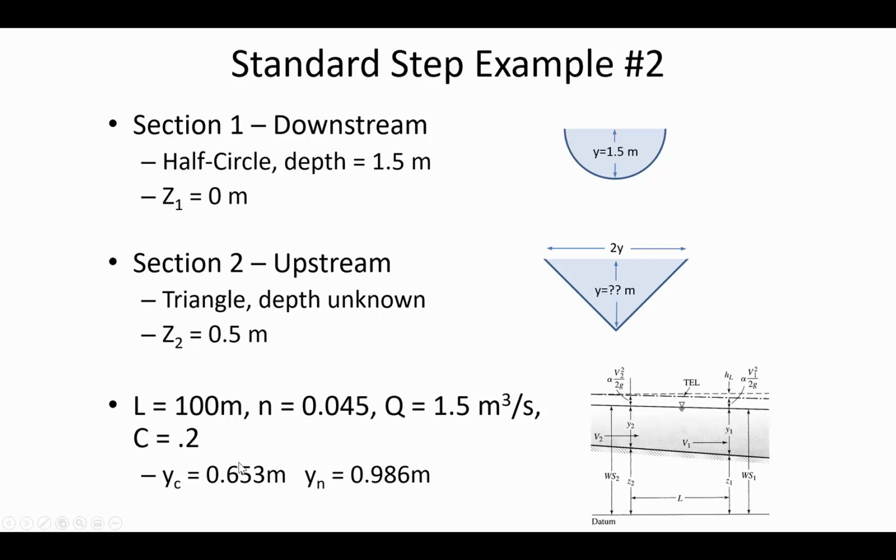So in other words, this is a channel that would support subcritical flow. That's a mild slope. And a steep slope is one that has supercritical flow. Anytime the normal depth is less than the critical depth, you're going to have supercritical flow and it's a steep slope. Here, because normal is greater than critical, that means it's a mild slope. And then since the given depth, 1.5, is greater than either of those, that puts it into zone 1. So it's an M1 profile.